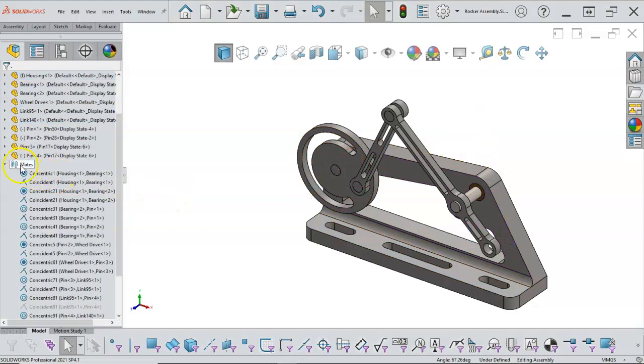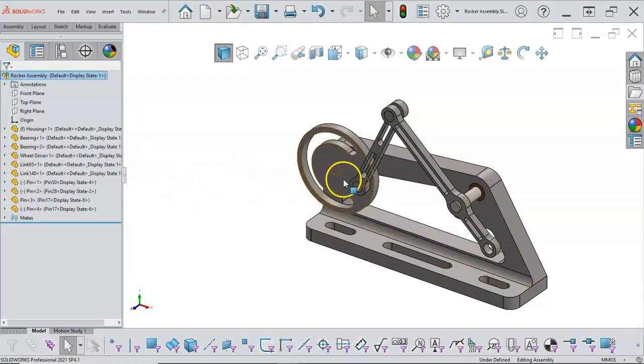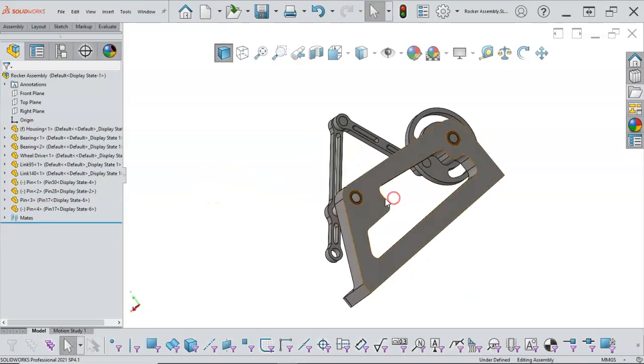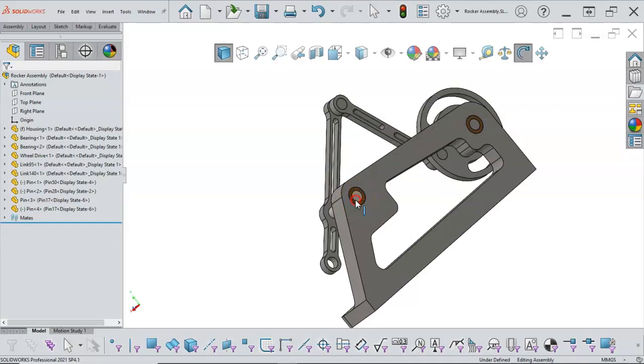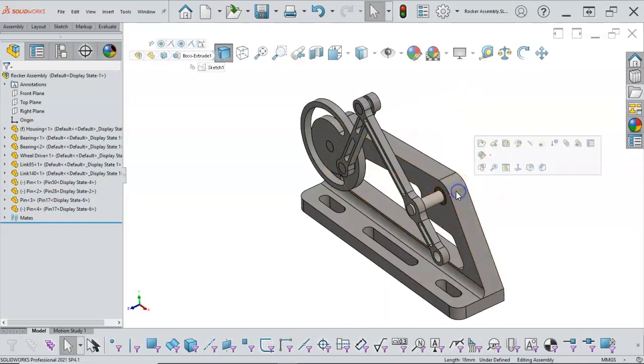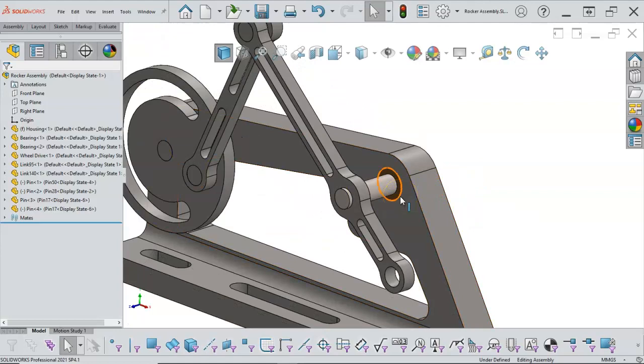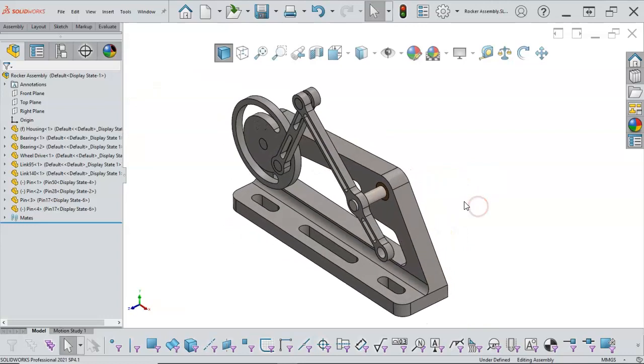The main goal is that we don't have anything moving that we did not intend for it, or possibly flip over in our assembly drawing. So close enough. If we stayed with the 35, we would have that gap. So I don't really want to, mechanically, I want at least 1 times D. So being 10 millimeter, we need to have 10 millimeters of engagement. With this filling it up at 18 millimeters, we're okay with the, almost 2 times D as far as loading support going through that geometry.